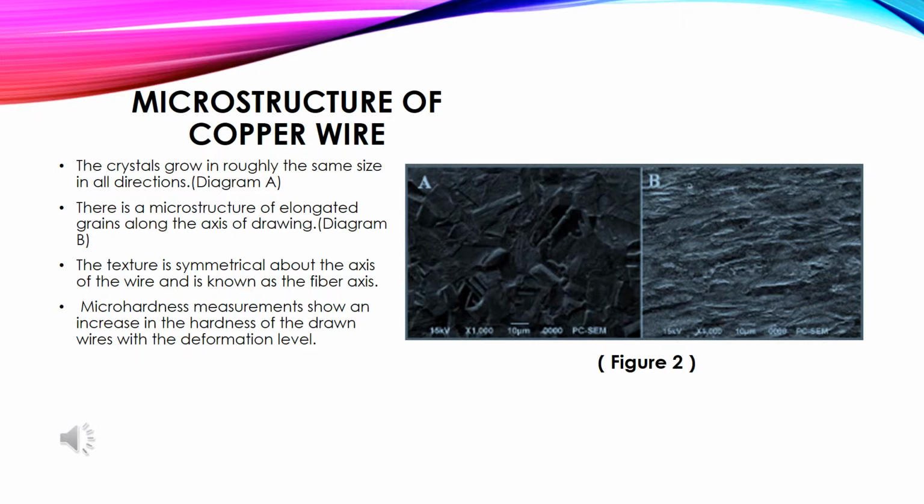Oxygen remains in the structure as cuprous oxide, but the majority of the structure is pure copper. The copper metal solidifies from the liquid state by the growth of crystals. The crystals grow in preferred directions and form open tree-like structures called dendrites. The dendritic structure is very typical of cast metals.